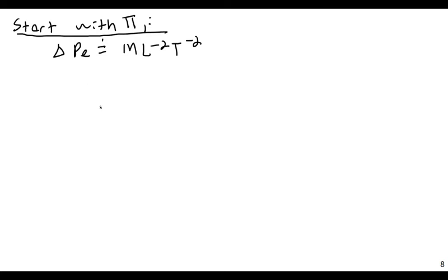And actually creating the pi terms can also be tricky because it's a certain amount of trial and error, figuring out what kind of power you need to take them to, that kind of thing. Or you could use some matrix methods if you want to get some simple solutions or to guide your analysis if you wished. It can get quite complex in certain cases. So what happens if I were to try maybe dividing by rho? Let's try working with rho.